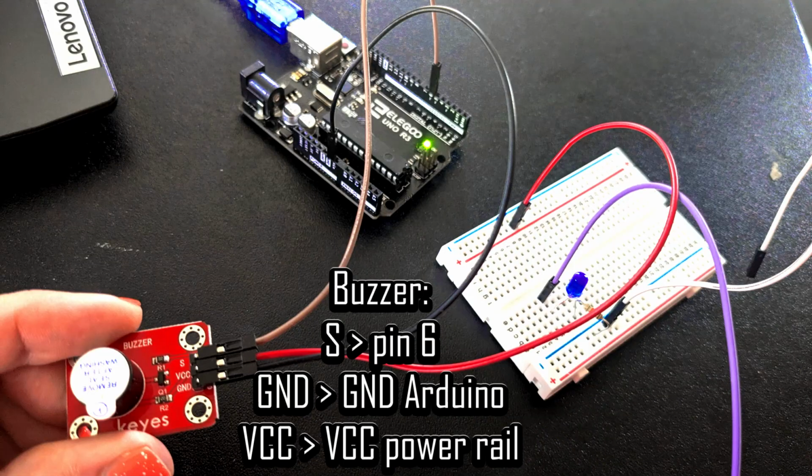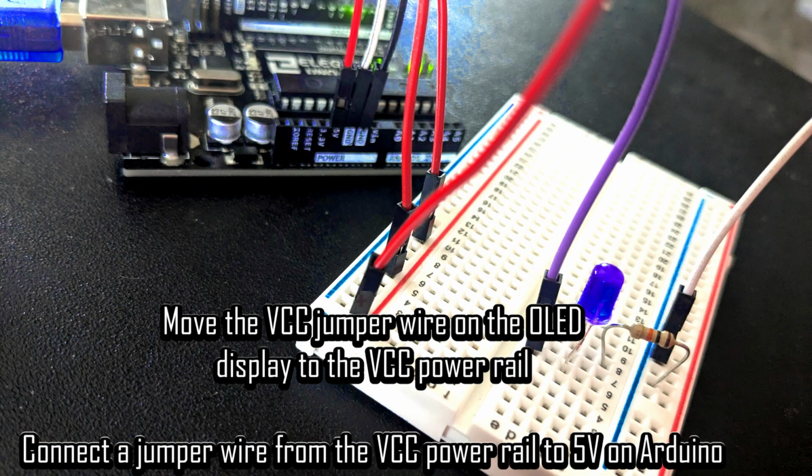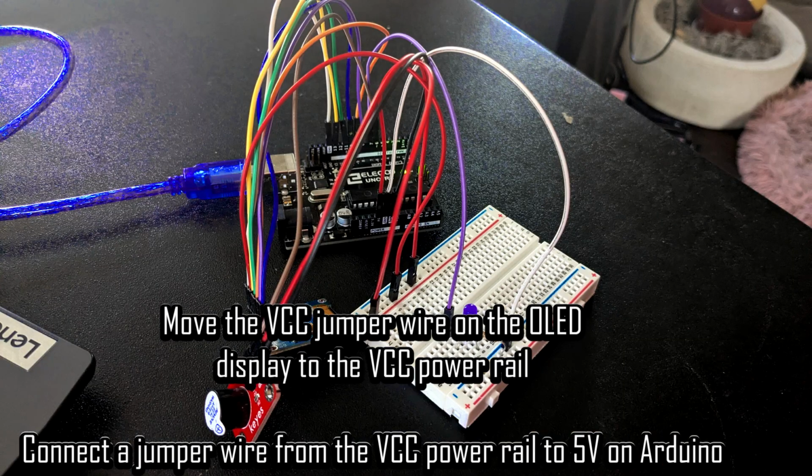For this second project where we respond to the aliens, we're going to add a buzzer. Keep most of the setup the same, but connect the S pin of the buzzer to pin 6 and the VCC lines of the buzzer and OLED display to the VCC sign on the power rail. Then connect a jumper wire from the positive sign of the power rail to 5 volts on the Arduino. Also connect the ground pin of the buzzer to ground on the Arduino.